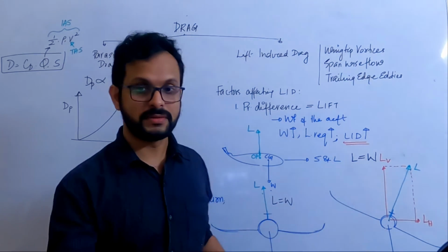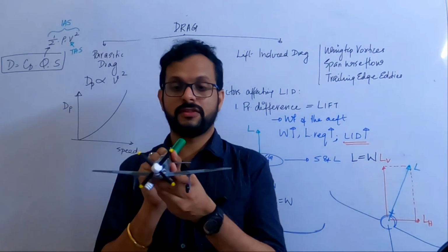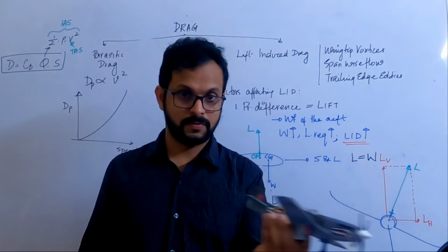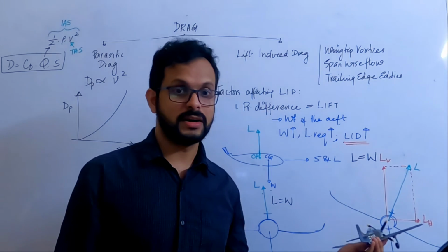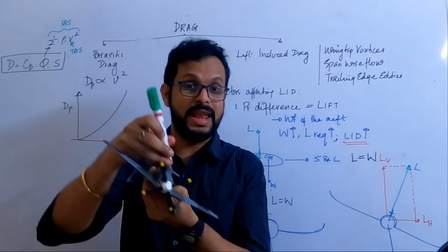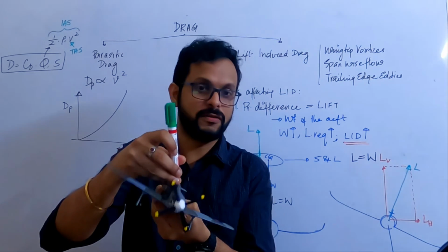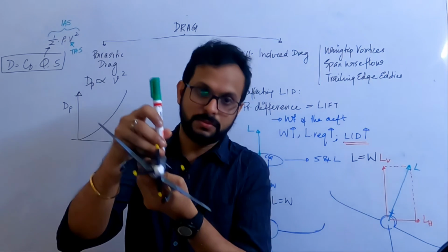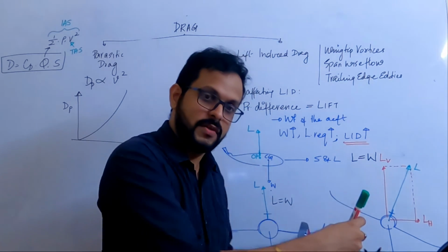No. So what happens is, if you start turning and you don't do anything about it, it's going to descend. It's going to turn, but it's going to do a descending turn, because now the weight is countered only by a lesser vertical component of lift. It's not that the aircraft will fall, it's going to make a very shallow descent all the way down as you turn.